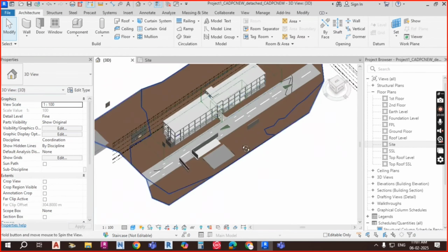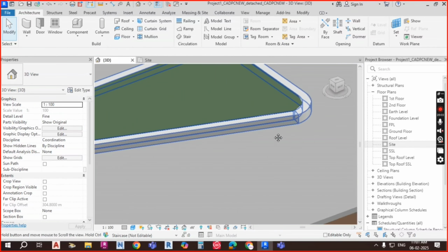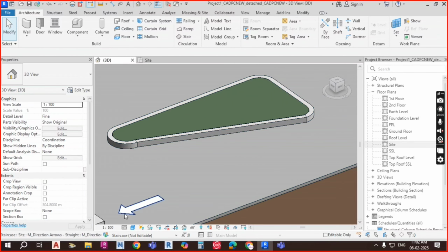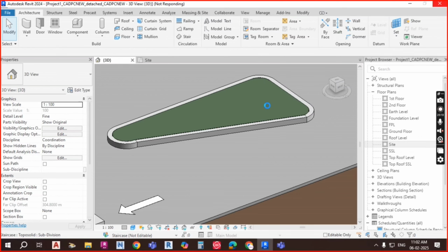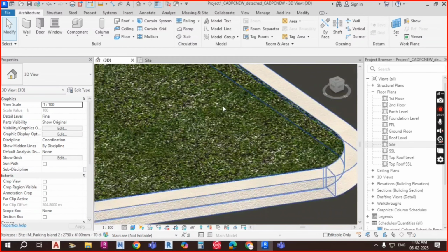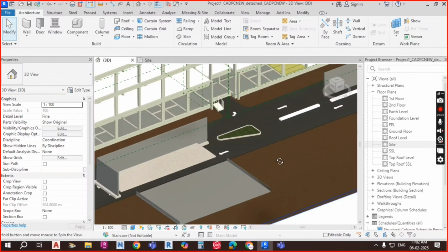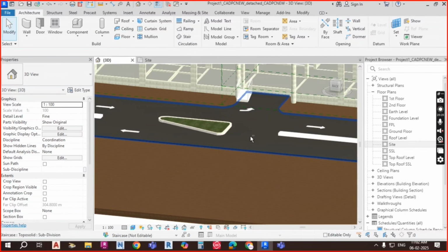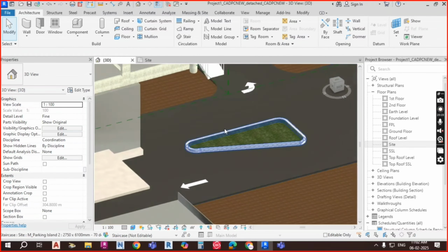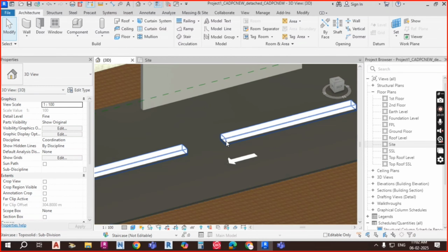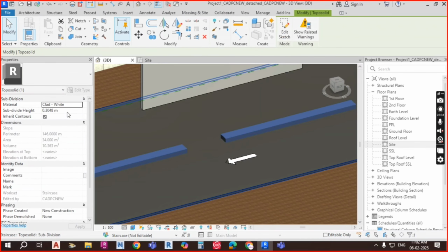If you go in 3D you can see some of the islands there. This island consists of grass and surrounding it is a compound foundation. You can go to realistic and you will be able to see the island and this strip, everything visible in a realistic view. Always when you are working here, you can see this is all the grass, and between the road you can see this is your road, and this is the parking sign, and between the parking signs you are placing some thickness. This thickness you have to make small, some 2 mm or like that.